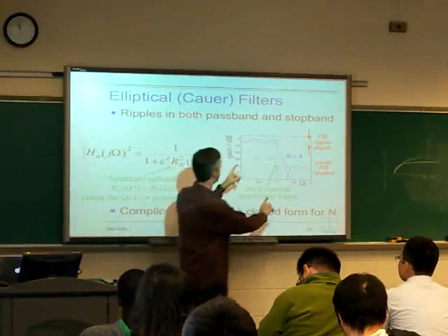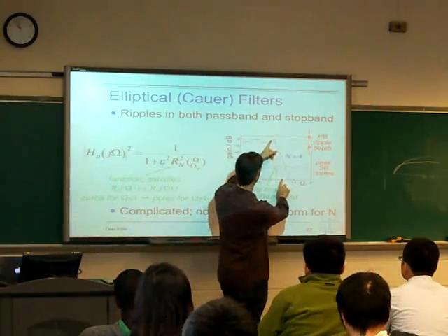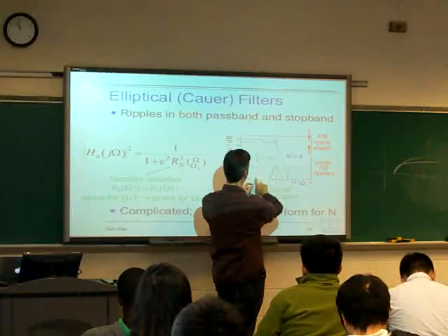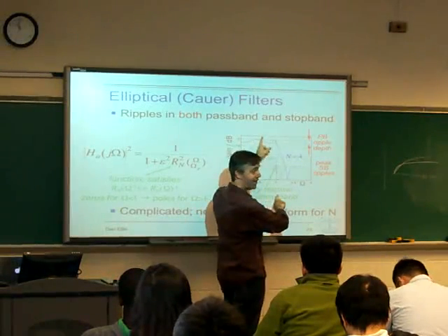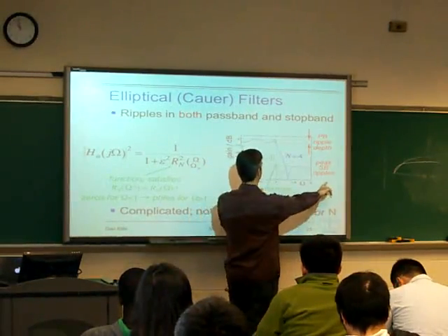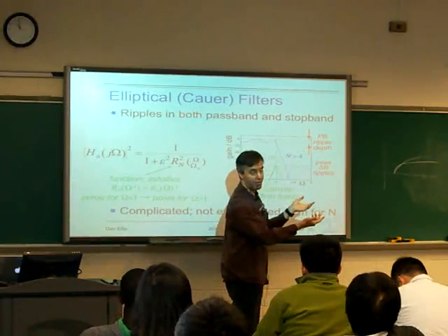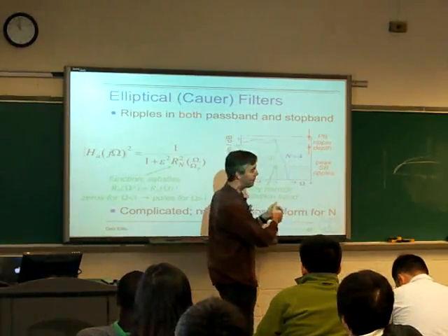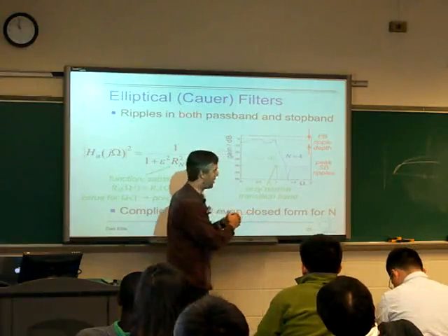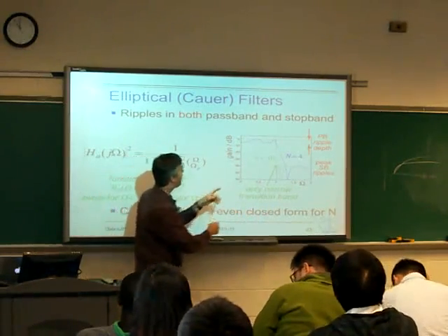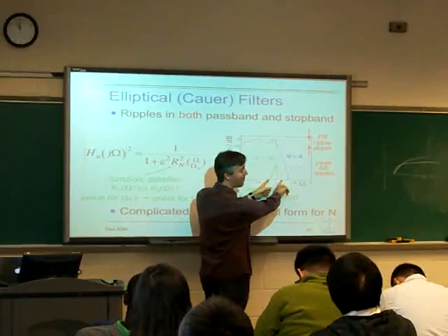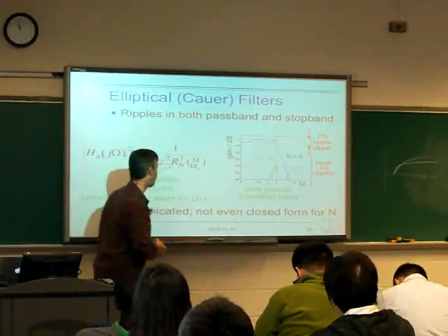And so that's what happens here: we end up with these reciprocal positions of the poles and the zeros. If there's a pole somewhere around omega equals 0.4, then there's going to be a zero out here at omega equals 1 over 0.4, which is something a little bit more than 2. This one here at 0.9 has a corresponding zero at 1.1, say.